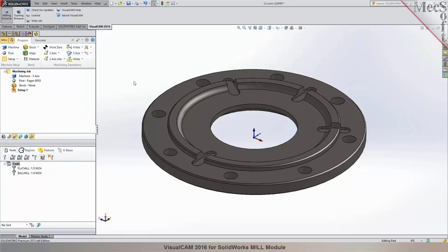Okay. All right. So the next step is, since we changed the orientation of the setup, it's flagged dirty, so we just right-click and regenerate. So that'll update the setup to ensure that the orientation for machining is defined, so it's normal to the space right there. We are now ready to create the stock geometry in here.